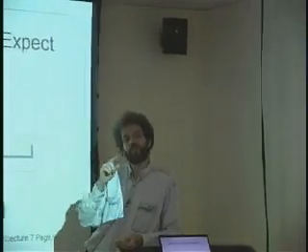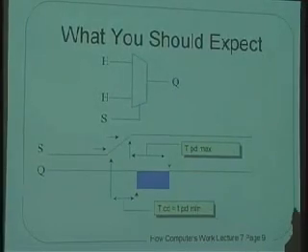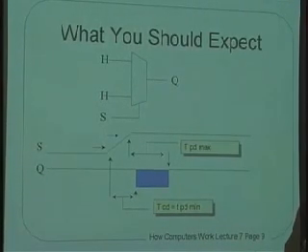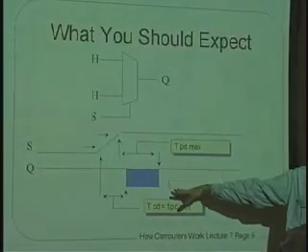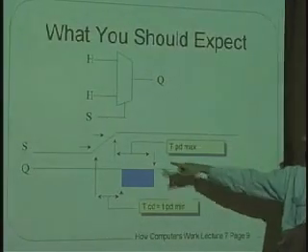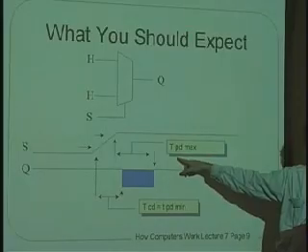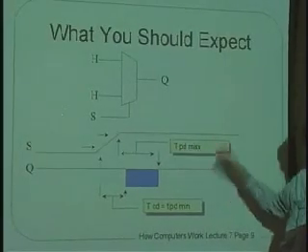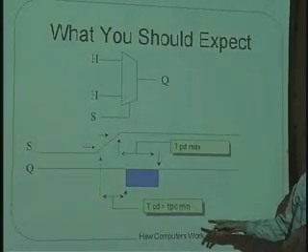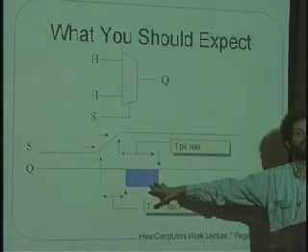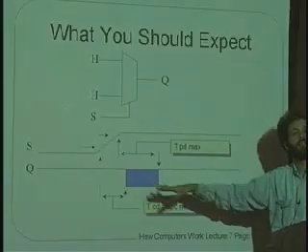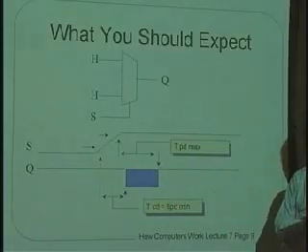If you remember our finite state machine timing diagram, that D flip-flop, the D register, did not sample its input until after all of this blue time was done. It waited until the TPD max had finished of one circuit, and then the next one, and then the T setup was done, and then we triggered it. Okay, so it's okay for these glitches and stuff to go on, as long as we're not watching the signal when it's going on.